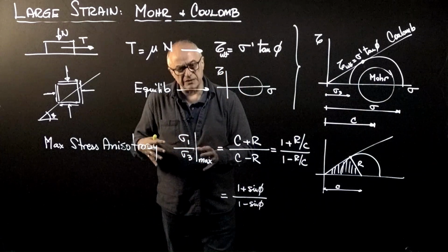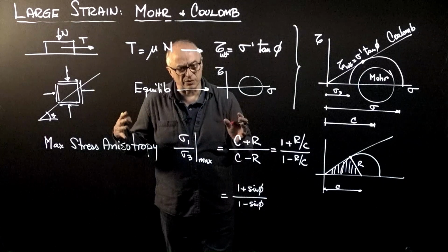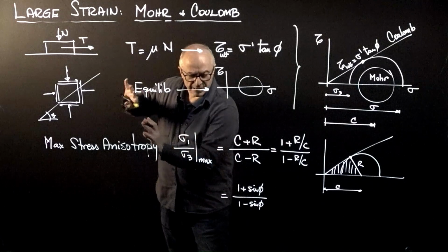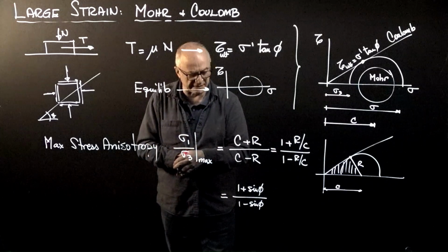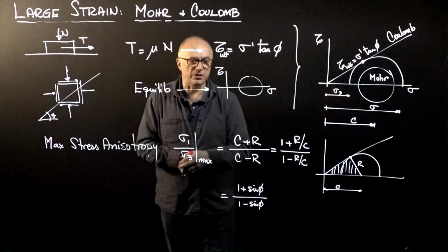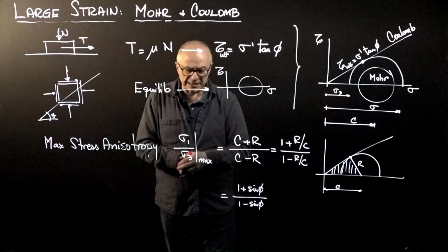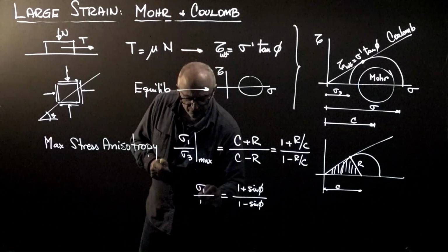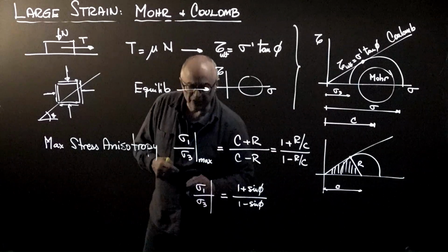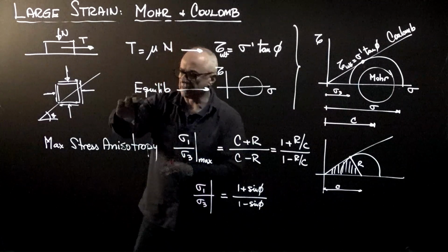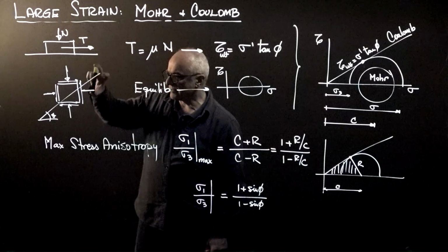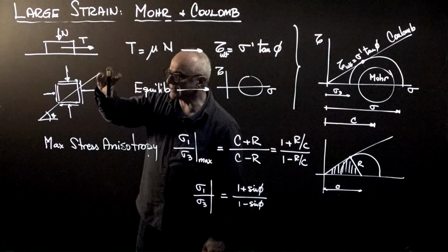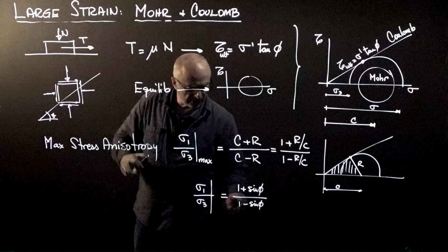You may have seen this also when we talk about retaining walls, whether we push them or where we release them. The maximum force that we can put for the system to passively resist is this stress anisotropy. We call it K passive. But really, the important thing I want to highlight here is that a soil, for being a granular material, cannot take infinite stress like this pencil. I can push this pen with very high force with zero lateral confinement, so it has infinite stress anisotropy. I cannot do that with the soil.